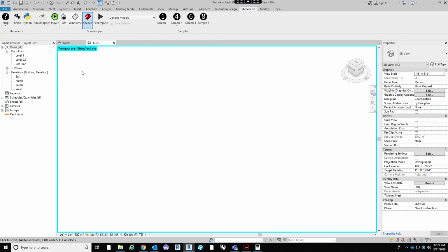And so the way that we're going to set this Grasshopper script up is it's going to be very specific. We can specify each different Revit element that we want to import: floors, walls, roofs, mullions, etc. And import those under specific layers. So we can also do some layer organization before we import the geometry into Rhino.